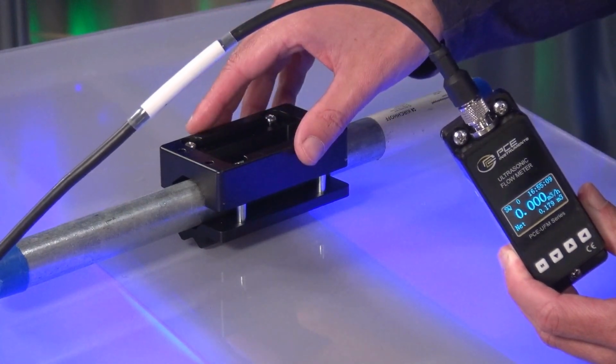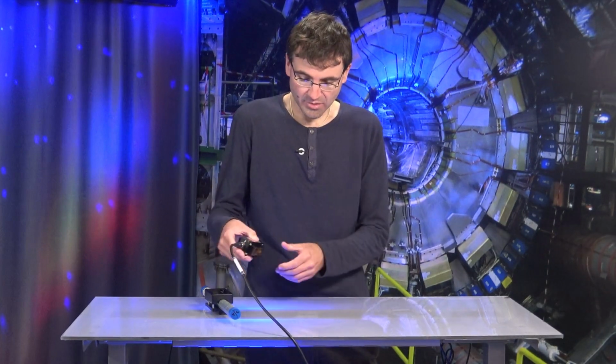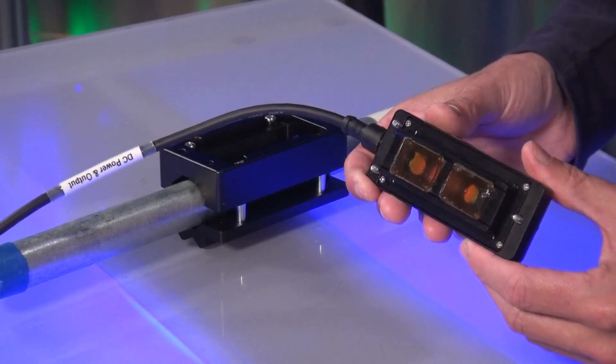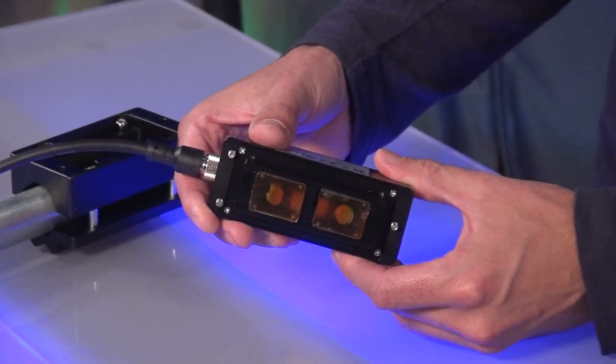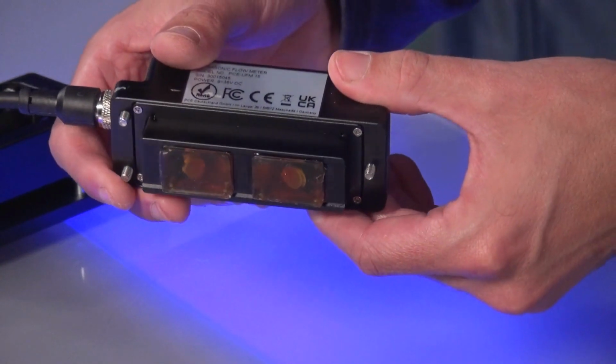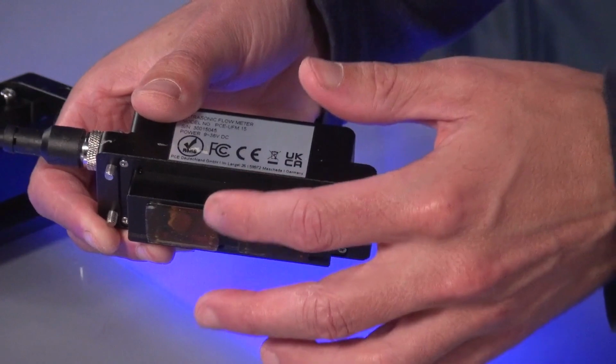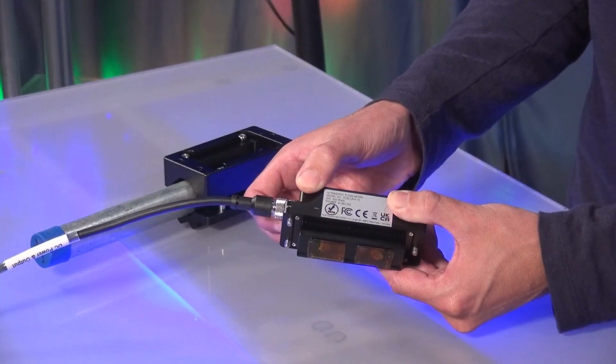In practice, we would now screw this holder in place, but we will now skip that for the purpose of this demonstration. The measuring device is now attached on here, but first I would like to show you this. So we have the piezo sensors down here again, one transmitter and one receiver. And on these sensors, if I turn this to the side, we can see a kind of foil. These coupling pads are important for ensuring that the sensor rests directly on the pipe without an air gap.